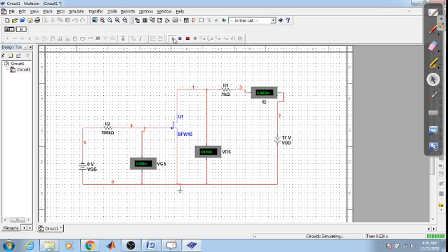Okay. Now your VDS is 10 volts, right? So let us enter this in the tabular column. So our VDS is 10 volts. Now vary the VGS. We need to vary the VGS in steps of 0.5 and note down the corresponding values of ID. So for VGS equals 0 volts, we need to make this VGS 0 volt.